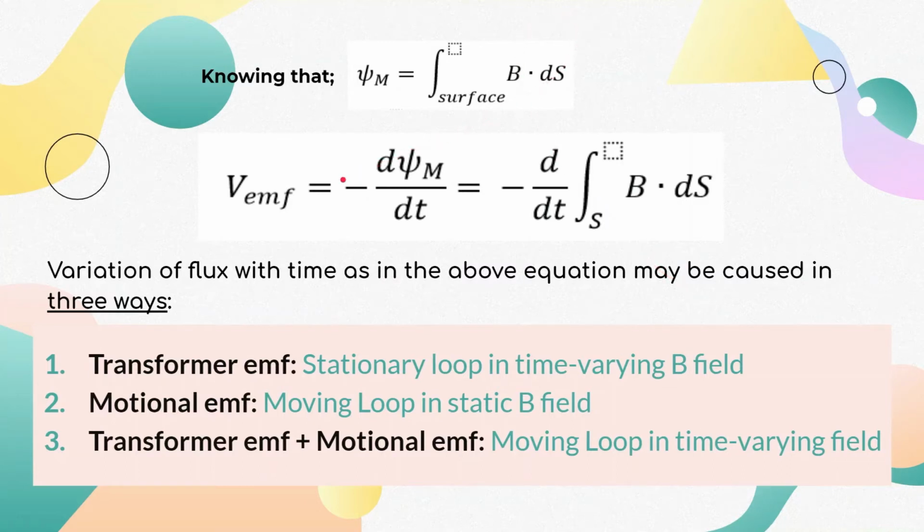If we set the number of turns of the circuit N equal to 1, then we get this equation over here. Knowing that in lecture 17 we have already learned that in a magnetostatic field, the magnetic flux is equal to the integral of the magnetic flux density, when we substitute it inside Faraday's law equation, we get this equation.